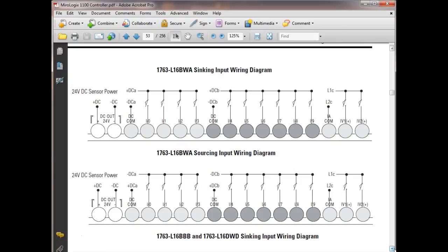So this, our inputs are what? The input, source. No, well, the devices, you're right, the input ports. We have the minus hooked to the common, so these guys are what? Well, sinking. We got the minus to the ports themselves. So this is the common for the ports right here. So if we have the minus hooked up to the ports, then my input ports are sinking. And then up there, when I hook up my input devices, I have the plus up there, so my devices themselves are hooked up to source. Y'all understand that?